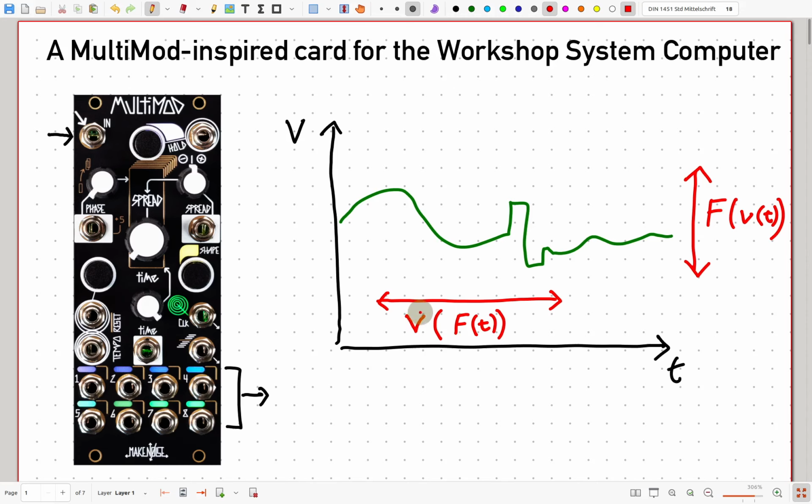And that's quite an interesting concept, I think, because of course, in a modular system, that voltage can represent any kind of signal. It could be a note pitch as a volt per octave signal. It could be some discrete gates, just 0 to 5 volts. It could be some CV which is representing the volume or the timbre or any other property of the sound. It could be an amplitude which goes into a VCA that controls the amplitude of another CV, so it could be a sort of second order control that affects how much another CV affects something. So lots of different meanings that a single voltage could have.